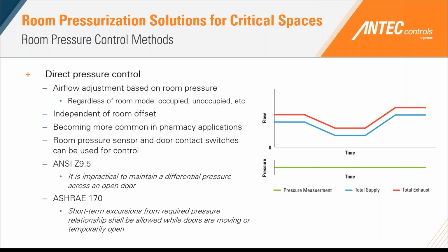When that door is open, it introduces a very large hole into your space, and it's very difficult to maintain that pressure set point while it's open. ASHRAE 170 also states that short-term excursions from required pressure relationships shall be allowed while the door is open or moving.